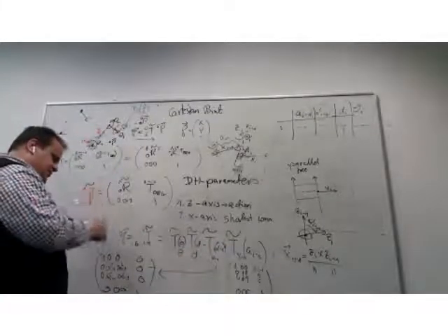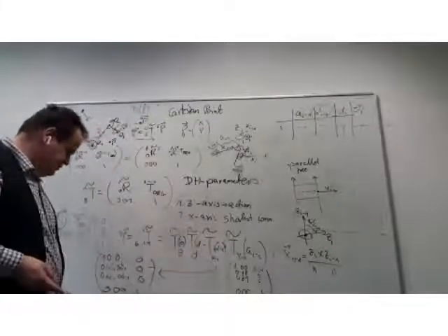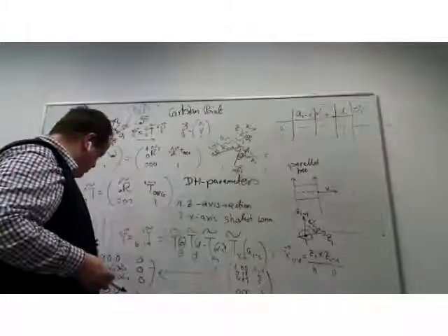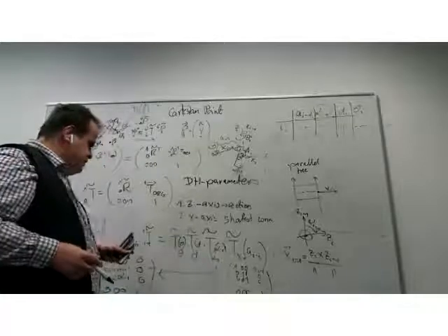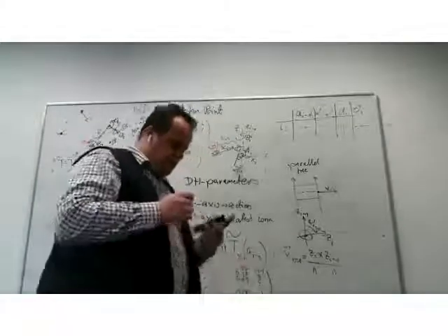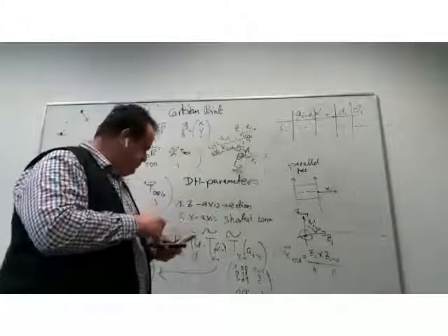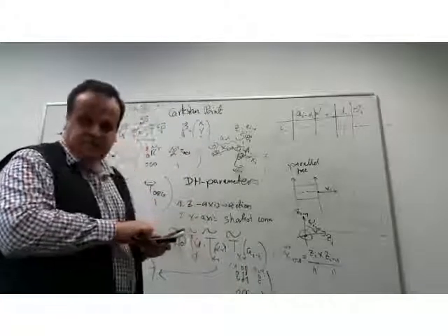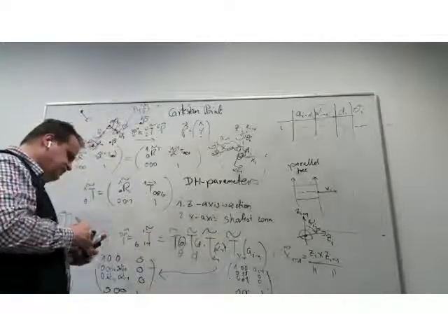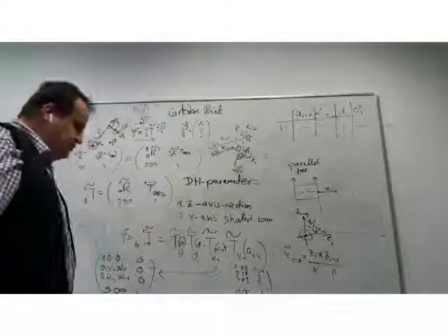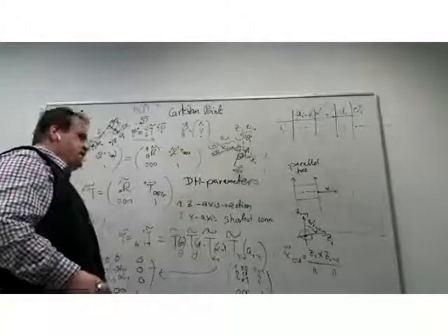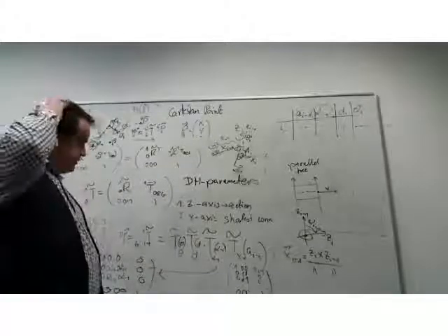In this resulting 4x4 matrix we still have the structure 0, 0, 0, 1 on the bottom and the rotational part, and you will see the elements theta, d, alpha_{i-1}, and a_{i-1} showing up in it. And now, what I want to do to find the kinematics of the robot is just the following.